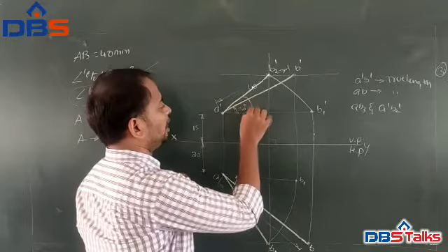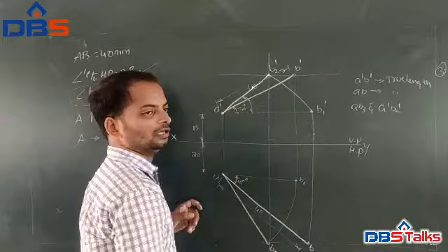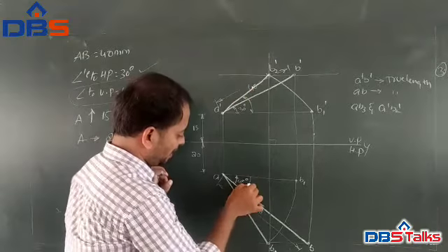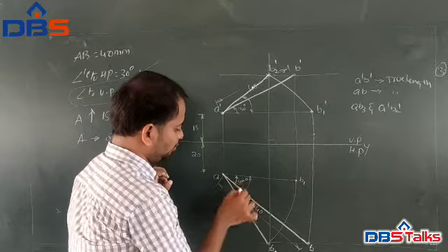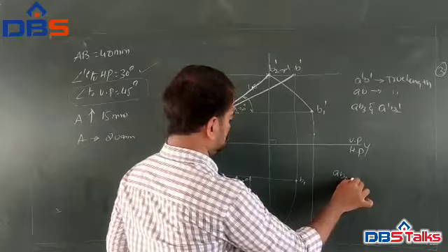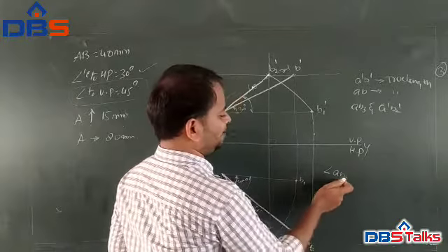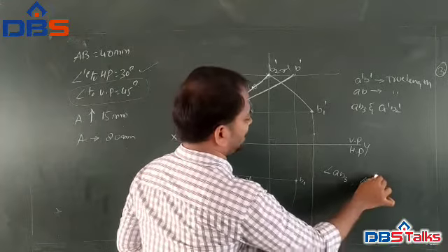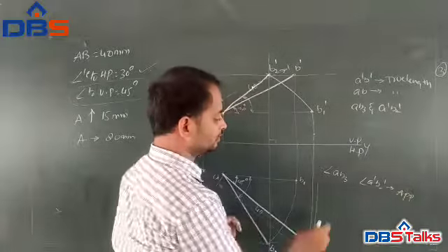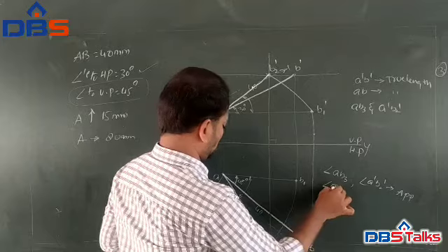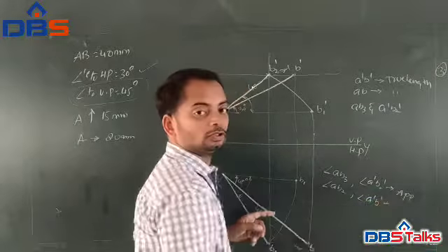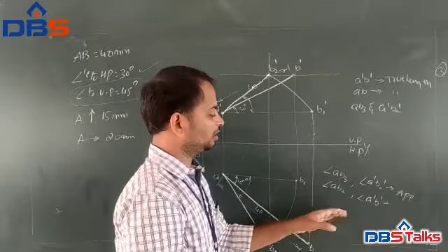So finally indicate the apparent angles of the problem by measuring the A dash B2 dash angle and the apparent angle of the top view also, that is AB2, this is AB3. Angle AB3 and angle A dash B2 dash are apparent angles. Next, angle AB2 and angle A dash B dash are the true angles of the given problem.